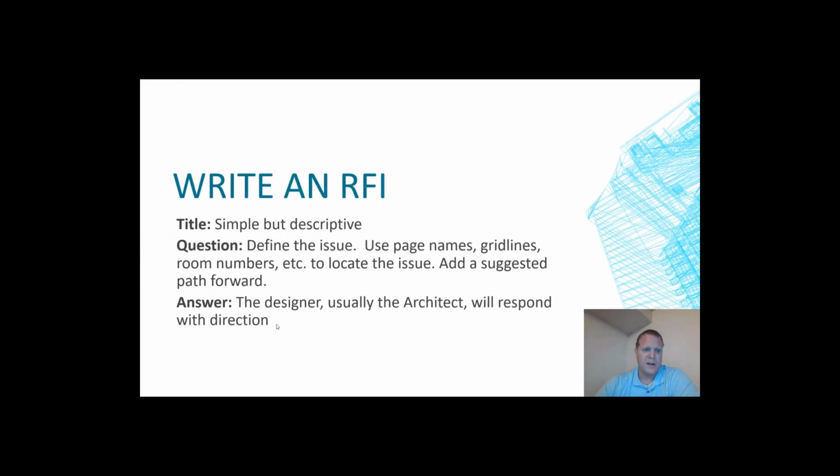I talked about writing an RFI a little bit. I didn't use all that. This is good notes. Page names, grid lines, I talked about that. Use room numbers, locate the issue. And I didn't do this, but add a suggested path forward.